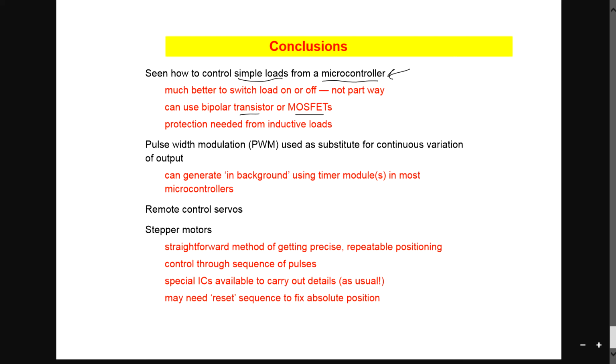So the bipolar and the MOSFET are something like a switch, so that if you supply a small enough current, you can actually open up the gate. If you still remember the bipolar, I won't go into details, but at least you get to know this. And just take note that whenever you design something for large loads, you need to be careful of inductive loads, because they cause a back EMF that can disrupt or destroy your system.